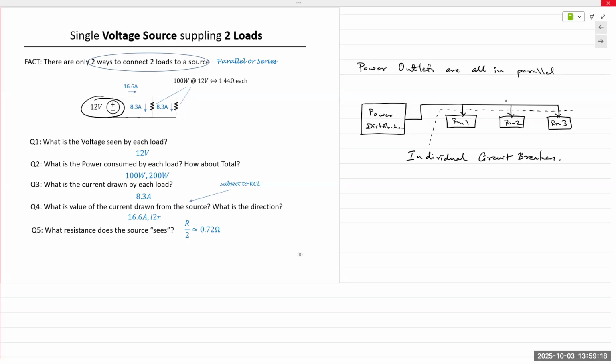Circuit breakers. There's a kind of like a solenoid relay in there. And then when it shorts, let's say if something happens, resistance goes low and it shorts and it triggers that relay. And so the relay is like a switch. Yeah. It's like a switch. And so that switch gets activated and so it breaks the connection.